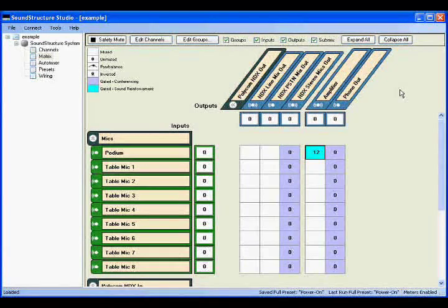Now, as we learned in a previous example, the echo canceller reference is set to amplifier by default. However, this causes a problem for the Podium microphone because the Podium microphone is played out the amplifier channel 2, which means now that the podium microphone is in its own acoustic echo canceller reference. This will cause the acoustic echo canceller to fight the podium microphone audio and will create a choppy version of